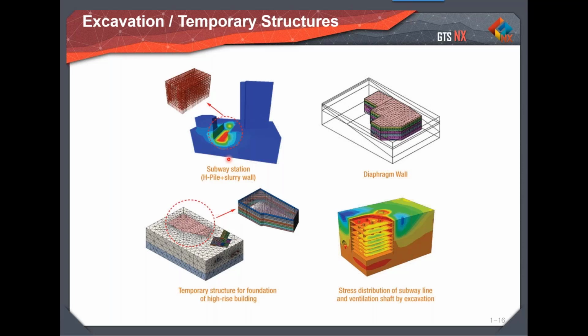And the next application is excavation. You can apply this software in all kinds of excavation lateral support systems. Suppose, let's say, if you're interested in applying the diaphragm wall, you can go for it. You can go for secant pile technique. You can apply the struts. You can apply wales. You can apply the plex and so on. So there is a lot of scope here. You can go for anchors, grouted and ungrouted as well, and a combination of both. So you can apply all such kind of techniques here.